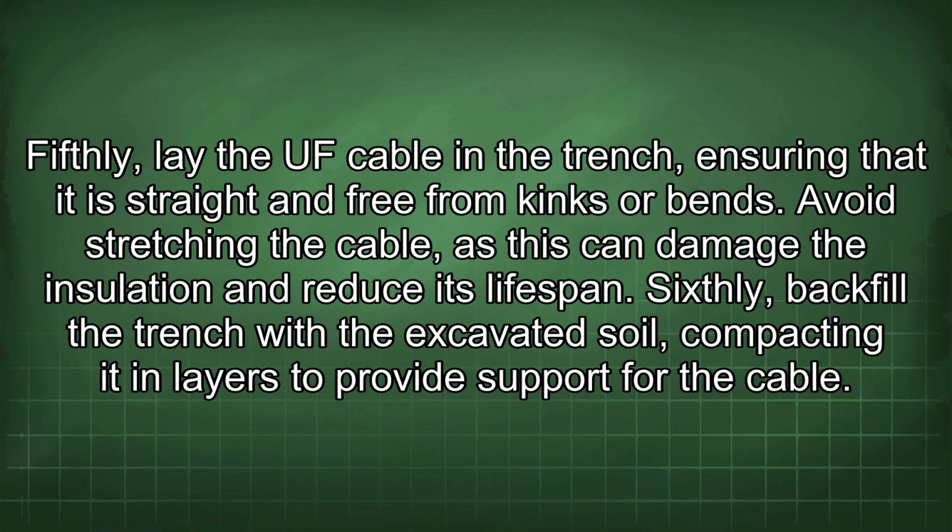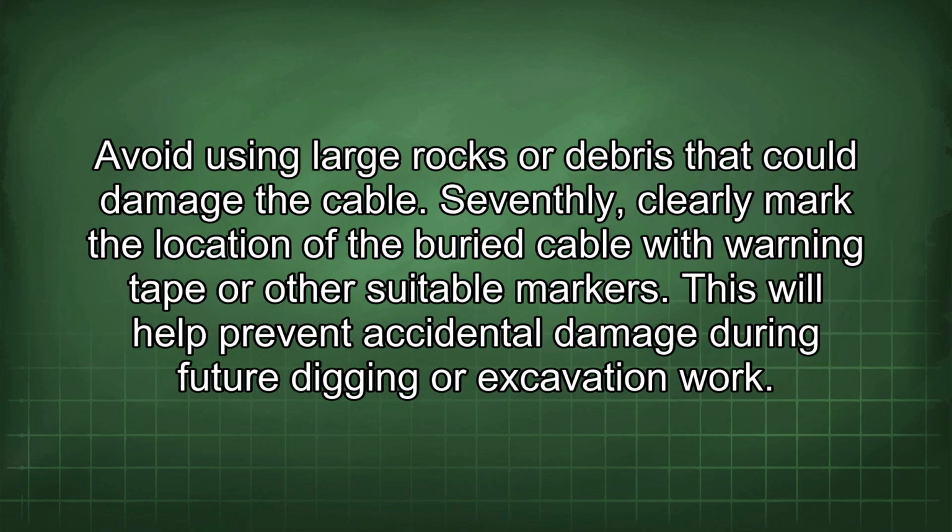Sixthly, backfill the trench with the excavated soil, compacting it in layers to provide support for the cable. Avoid using large rocks or debris that could damage the cable. Seventhly, clearly mark the location of the buried cable with warning tape or other suitable markers. This will help prevent accidental damage during future digging or excavation work.